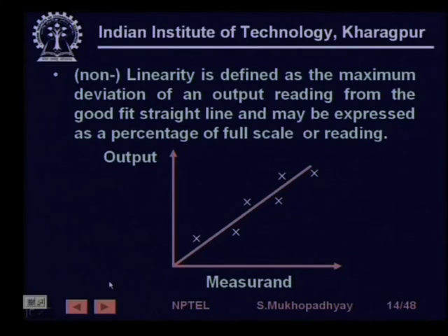So that it is the smallest possible, you have to actually take all the data and make a best fit straight line, such that the sum of square of errors is the least, or something like that. So, that's linearity: the deviation of the calibration data from some good straight line, which you have obtained either by data fitting, or in some cases in a different way.